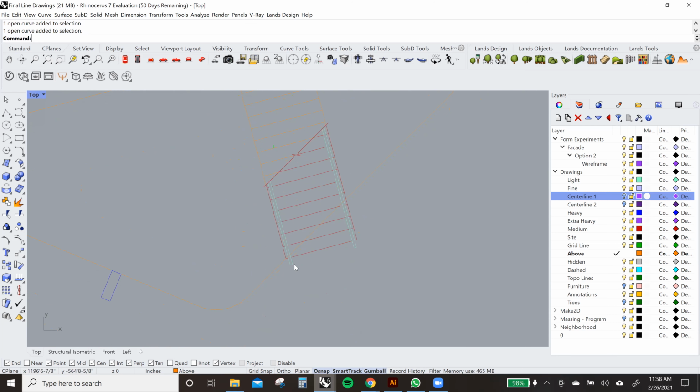And you cut some of the handrail details here. I think that's a really good example of the kind of thing that we don't want to include as extra. The handrails are worth including beneath the cut, but above the cut, they're not worth showing as hidden lines because at a fundamental level, it's an over-saturation of information.